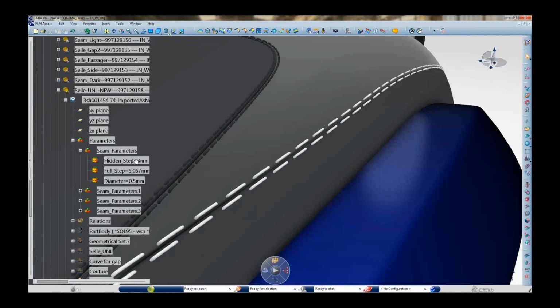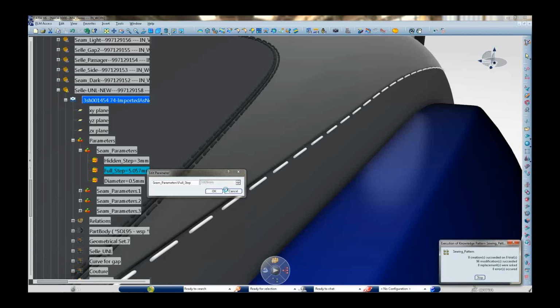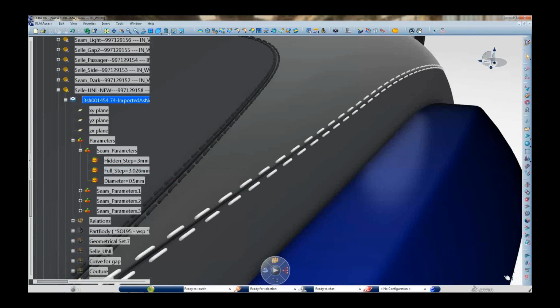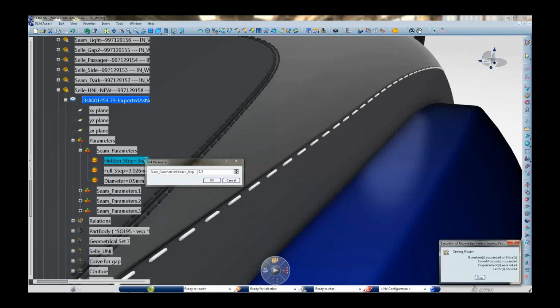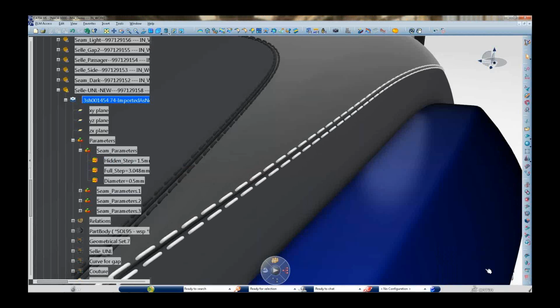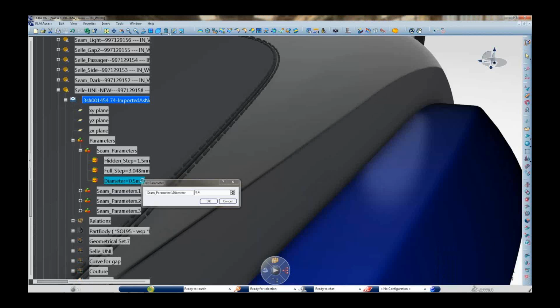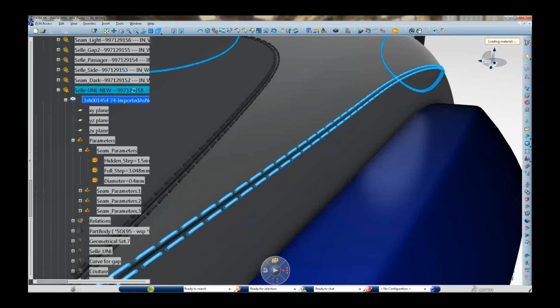And again, being integrated in CATIA means that you can use all the other tools of CATIA, like KnowledgeWare in this example, to generate automatically the stitching on this seat design. And you can use your subdiv surface for any other tools or activities like milling, rapid prototyping, or anything else. So it's an easy to use, very quick design exploration tool directly in 3D with a pretty good real-time visual feedback.